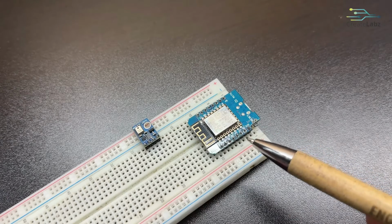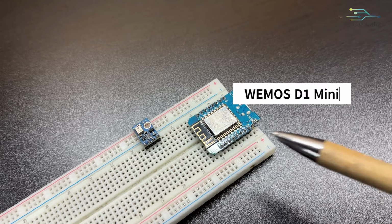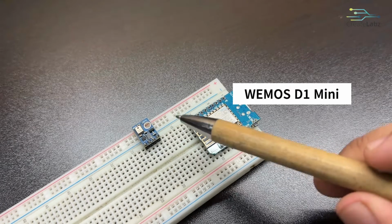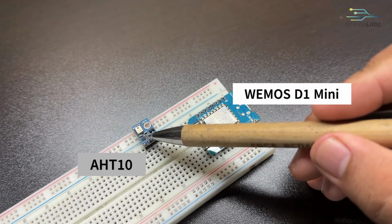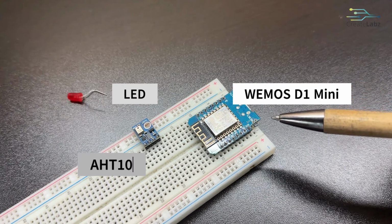For this demonstration, we are using the Wemos D1 Mini, the AHT10 temperature and humidity sensor connected via I2C on pins D2 and D1, and one LED connected to pin D5.